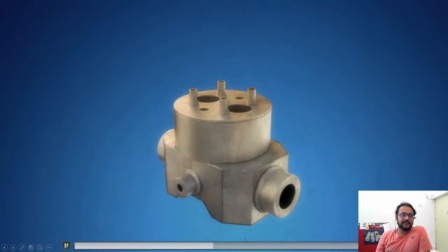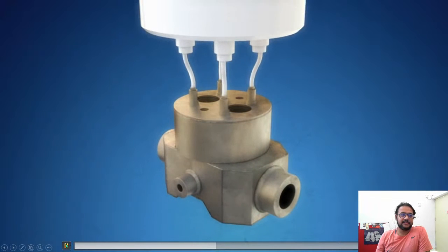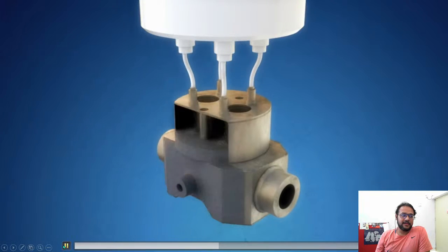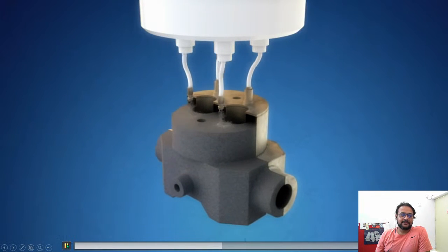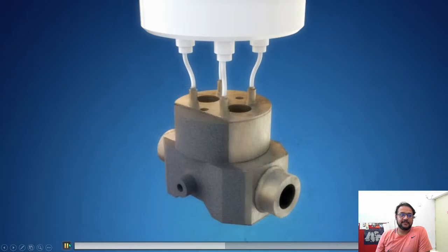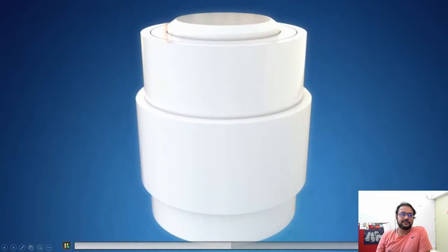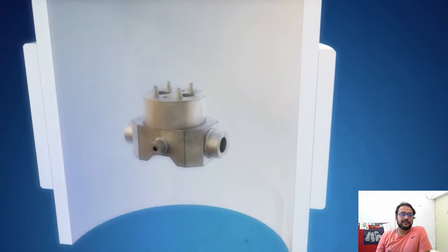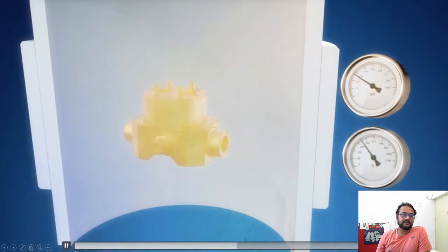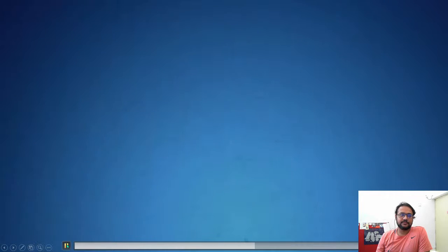The capsule is filled with metal powder according to a pre-calculated weight. The powder is packed by vibrating the capsule. After filling, the capsule is again tested for tightness with helium gas. Okay, so it is tested at two stages. Then the capsule is evacuated and inserted into a cylindrical hot isostatic press. This is where the hot isostatic pressing process begins. To obtain 100% densification, the capsule is exposed to high isostatic pressure using argon gas and high temperature. The volumetric shrinkage during the HIP process is approximately 30%.